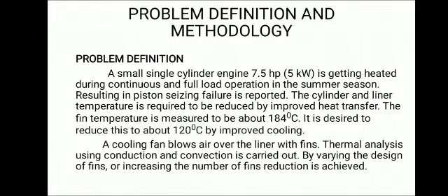Problem definition and methodology. Problem definition: a small single cylinder engine of 7.5 horsepower is getting heated during continuous and full load operation in summer season, and piston seizing failure is reported. The cylinder and liner temperature is required to be reduced by improved heat transfer. A cooling fan blows air over the liner with fins. Thermal analysis using conduction and convection is carried out.